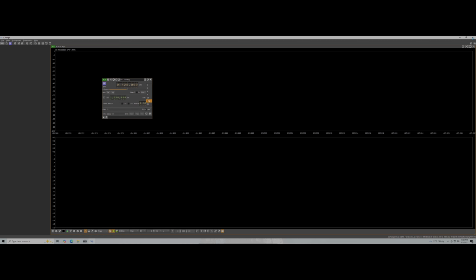And if you want, you can adjust your decimation rate down a little bit to 4 or 8. This should be fine. Either one should pick up a strong ELT signal, no problem. So you can just play around with these settings and see what you like more. We can leave the DC and the IQ correction as it is. Same with the local oscillator, PPM. We can leave that slider alone.